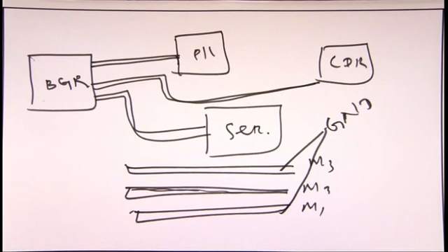So the immediate top metal layer and the immediate bottom layer are used as the guard layer, and they should be connected in common and then put to ground. So this will be shielded. Clear? Next one. This is one type of shielding. But what is 3D shielding?